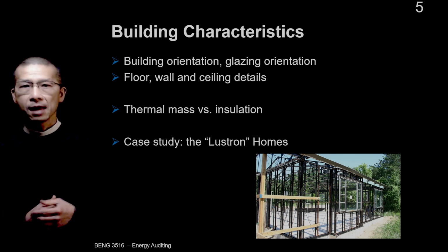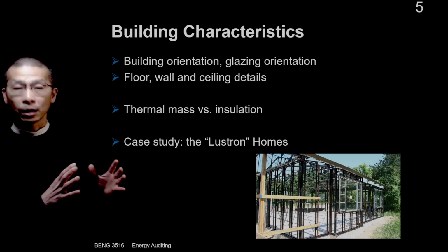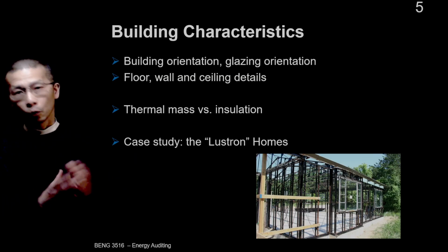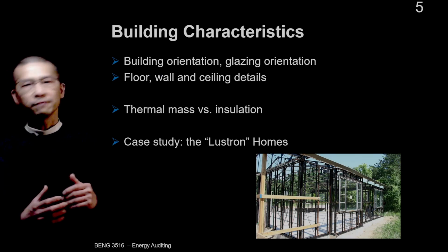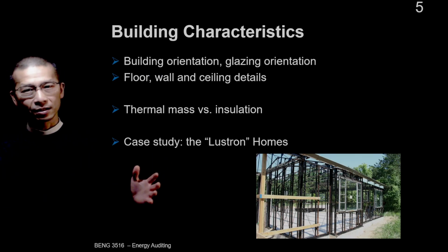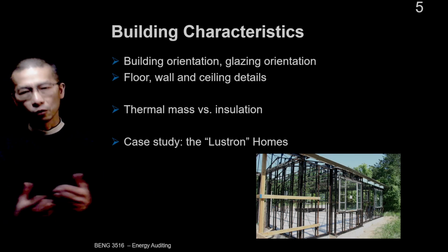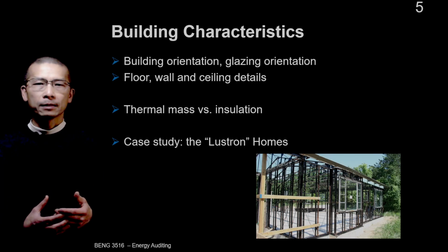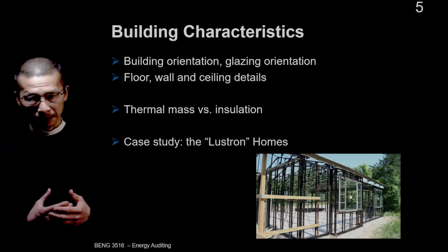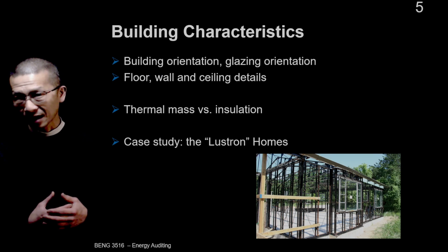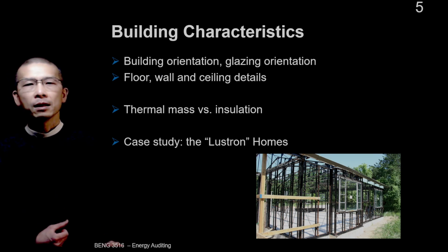We also look at the glazing, not only the building orientation, but also the window orientation. Not all windows are equal. A massive glass wall facing west would be an energy disaster for cooling because it catches the low, hot afternoon sunlight, whereas south-facing glass can be a benefit for heating.